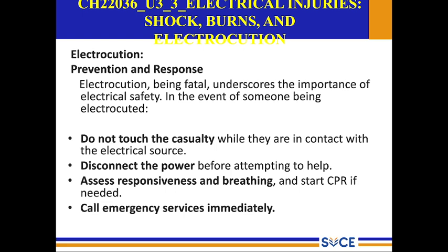Electrocution, prevention and response. Electrocution can be fatal, which underscores the importance of electrical safety. Do not touch the casualty. When you understand it is because of electricity, you should not touch them while they are in contact with the electrical source. Disconnect the power before attempting to help. Assess responsiveness and breathing and start CPR if needed. Call emergency services immediately when something is beyond your control.